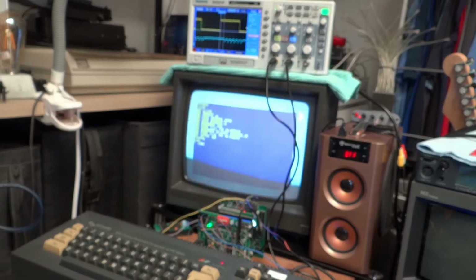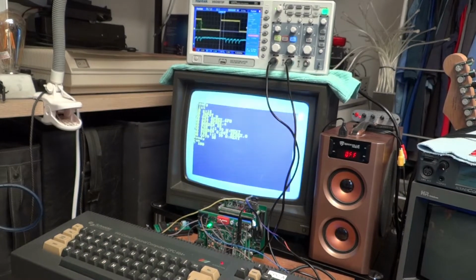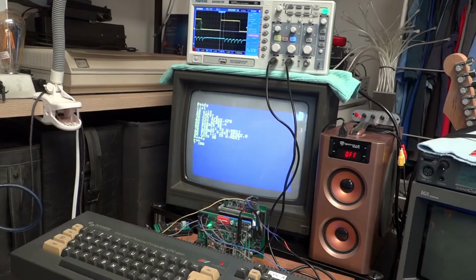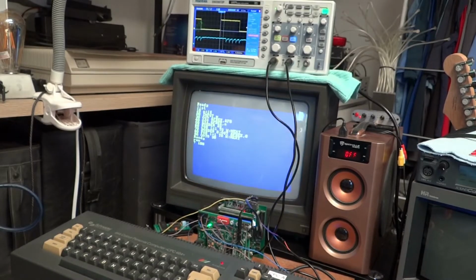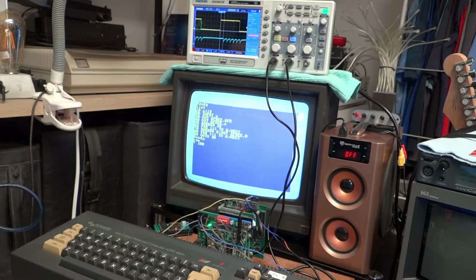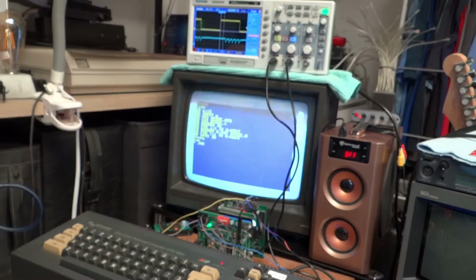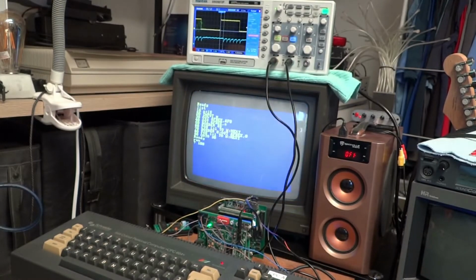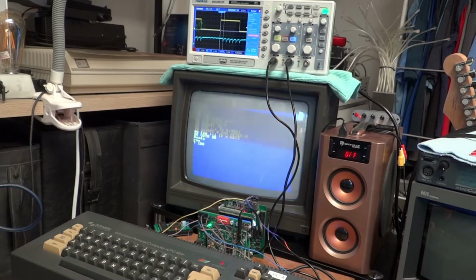With that, I think it's safe to assume, and this is of course an artifact of the missing synchronization between my digitally generated signal here, by the BASIC program, simply a counter, and the CRT, that on average we have 25 milliseconds of delay between the digital signal and the change in screen brightness.